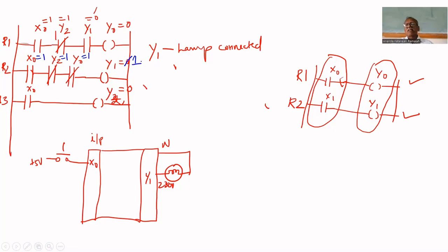Still, the key is being pressed, because it is 30 milliseconds. During that time, the program will be executed 30 times, because to execute the entire program takes only 1 millisecond. So the third time here also X0 equal to 1. Therefore, Y2 becomes 1. How many times will it be executed?